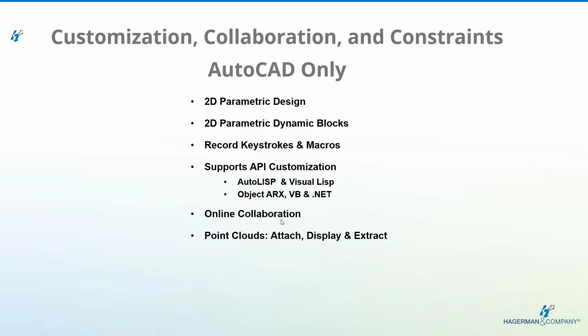In AutoCAD, you can record keystrokes and macros. In other words, there's a recorder built into it where you can start typing a command, make picks on the screen, and it will memorize everything you're doing. When you finish the recording, you can save that as a macro, and then come back later and replay it, and it'll do the exact same thing. You can add pauses where it requires user input, so it can be unique, such as a pause for picking a point or entering text.